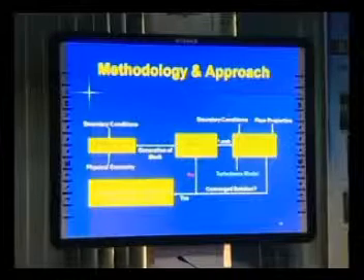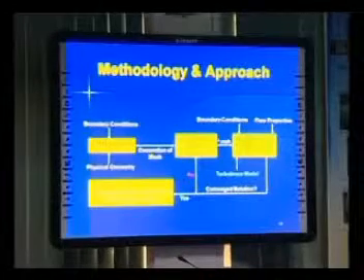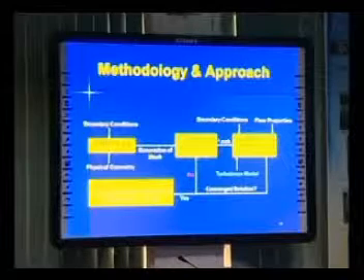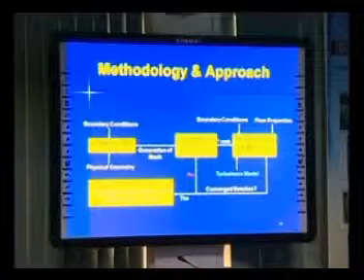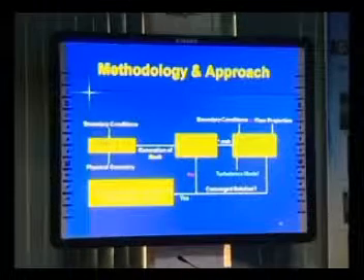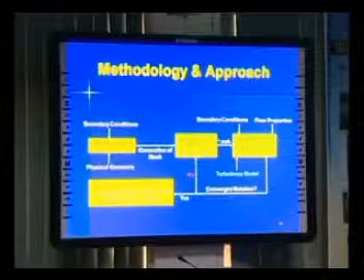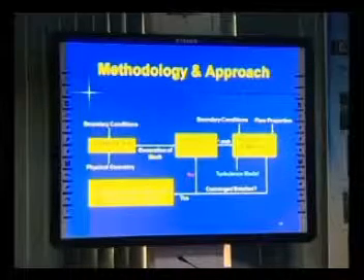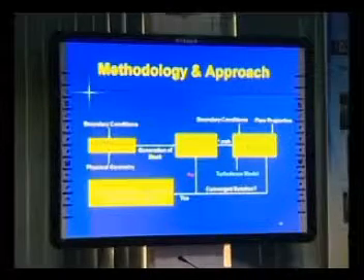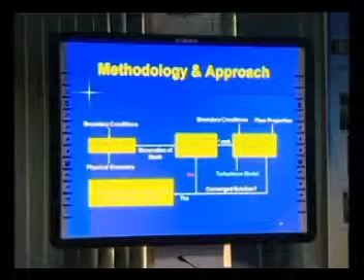And again, you have to incorporate the boundary conditions, the flow properties, the turbulence models, and all other applicable models so that you can run your simulations. If your simulation is successful, then you can generate a converged solution. This is not so easy, because in the middle your simulation can crash, and sometimes there will be stability problems.